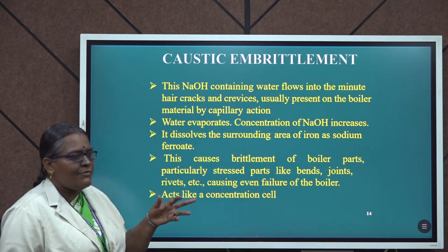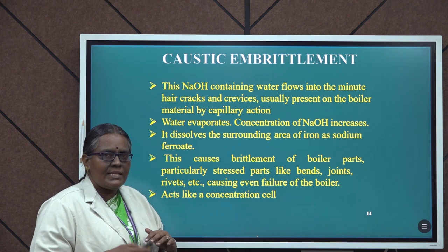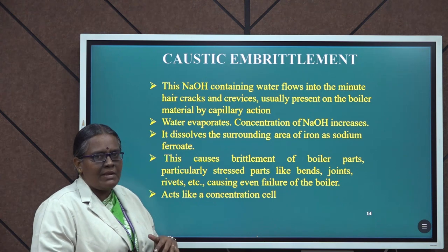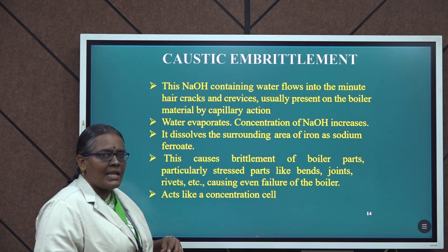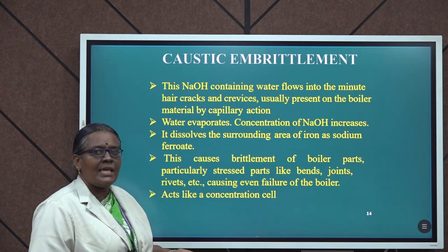So, the principle of working is similar to concentration cell. That is, the water inside the voids will have high NaOH concentration, outside will have a low NaOH concentration. So, it creates a potential and ultimately results in corrosion. It is otherwise called as caustic embrittlement.